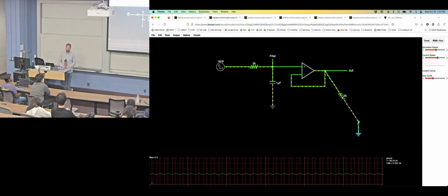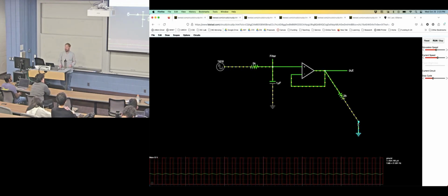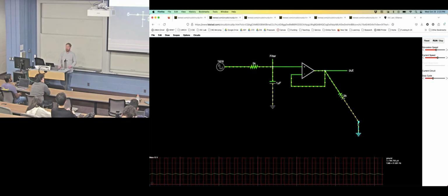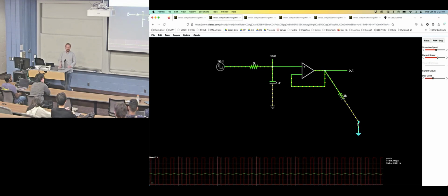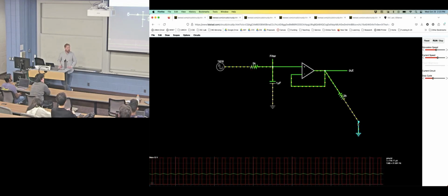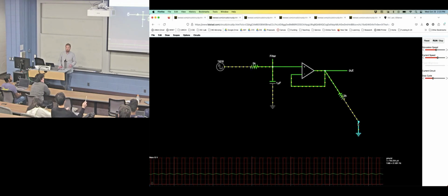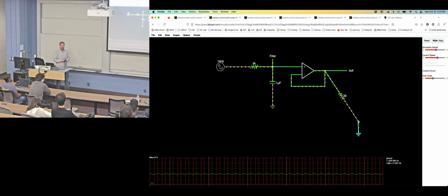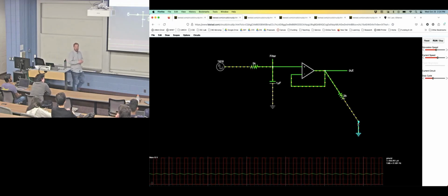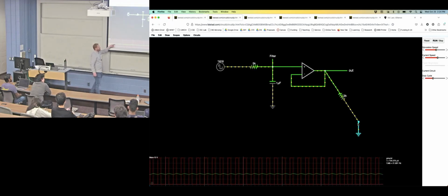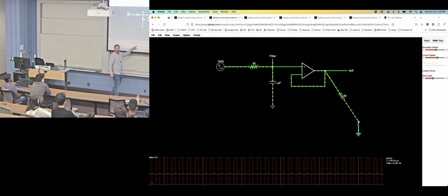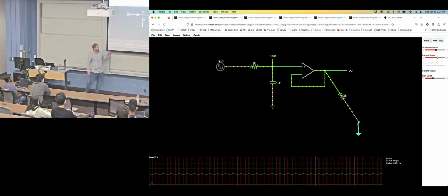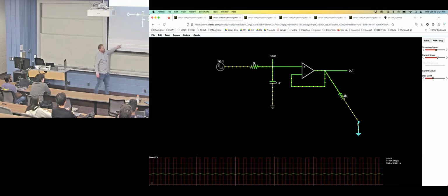Yeah. Simple. A capacitor, resistor, and a buffer can make this today. All right, you know PWMs, you can make a DAC. What are some of the bad things about this? Simple, okay. What does that translate to? What's the downside? Poor translation from digital to analog. We have some voltage variation here, right? It's not a nice constant. You want it to be constant. What would be one way to decrease the variation of this voltage?